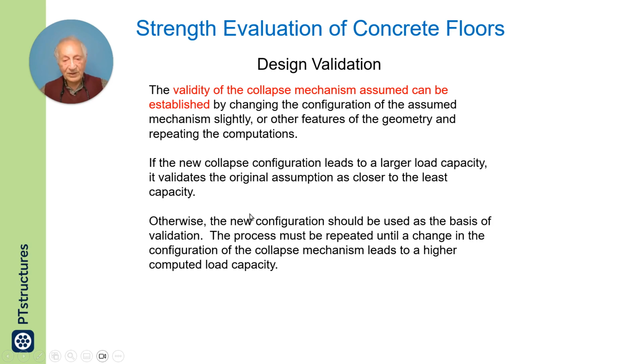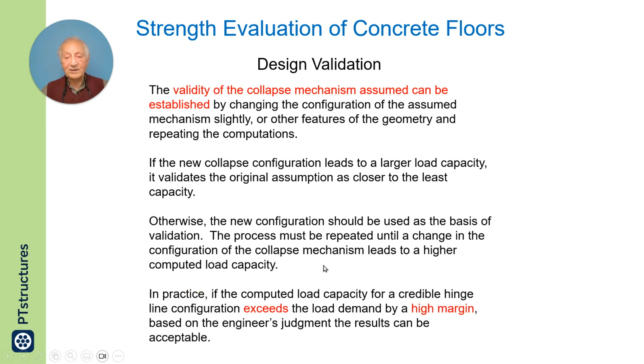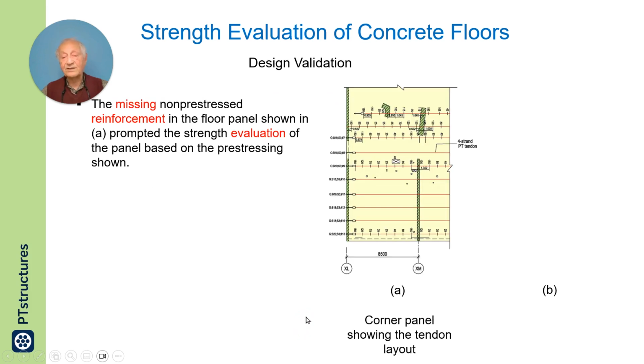Now, with a computer program, all this is very fast because you just use the mouse and click at point A, click at point B, and that will, in the background, create a hinge line, and then the capacity is calculated in the background. In practice, if the computed load capacity for a credible hinge line exceeds the demand by a high margin, based on the engineer's judgment, the result can be considered acceptable.